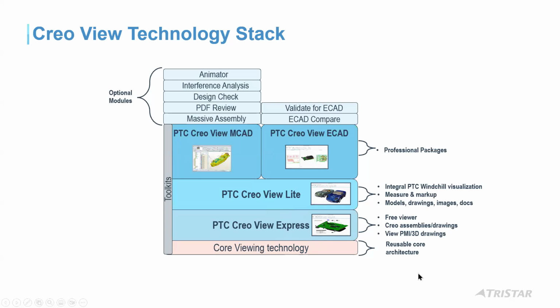So where would you use Creo View Express? Well, this is for someone you send files to that's not in your Windchill, or if you're not using Windchill, someone you send files to from your Creo session. You can export your Creo models or just Creo View models from your Creo session and then send that file out to somebody to take a look at. They just need to install Creo View Express and they can look at it.